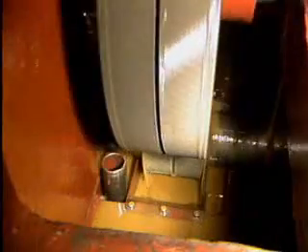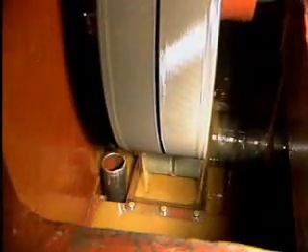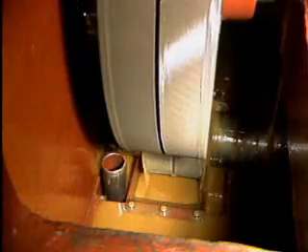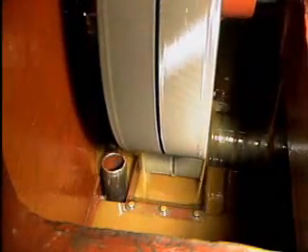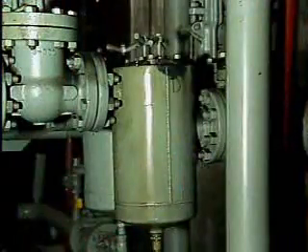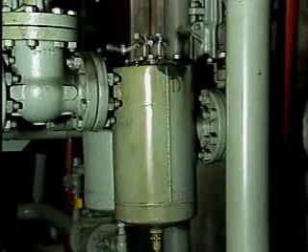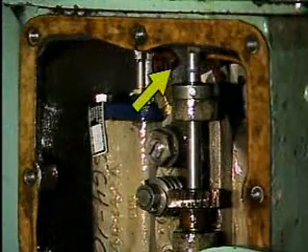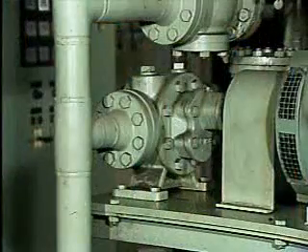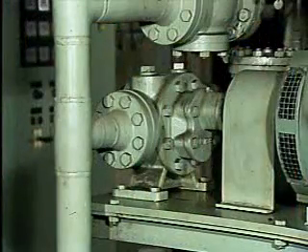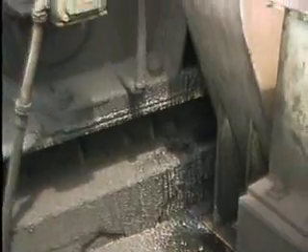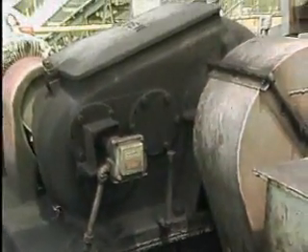If a lubricating system does not lubricate all of the gear's tooth surfaces before they mesh, overheating and excessive wear may occur. Insufficient lubrication can be a result of clogged filters, clogged or improperly adjusted spray nozzles, or the improper operation of the lubricating system. Also, lubricant can be lost from a gearbox through a blown seal or a leaking joint. As you might guess, a problem that develops in a gear set's lubrication system may end up damaging the gears.